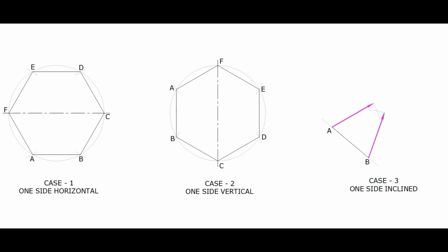Now this intersection point as center, draw a circle. You may notice that the circle will be passing through the end points of the first side. We have measurement of side of the hexagon in the compass. From the end points of the first side, cut arcs on the circle.